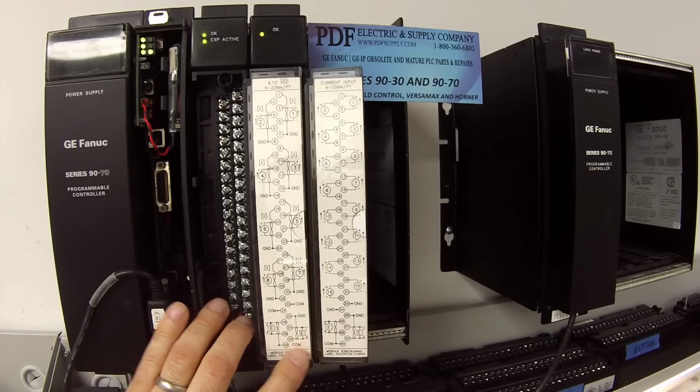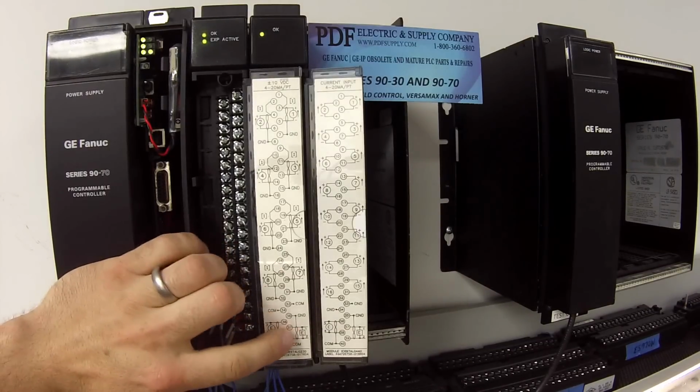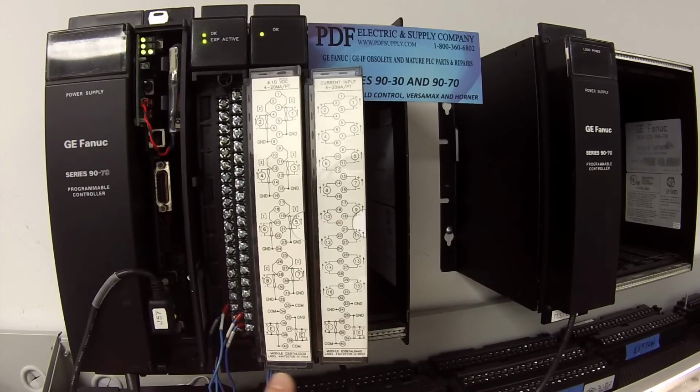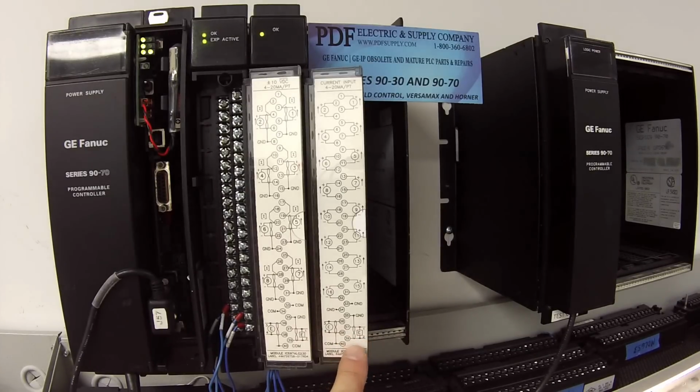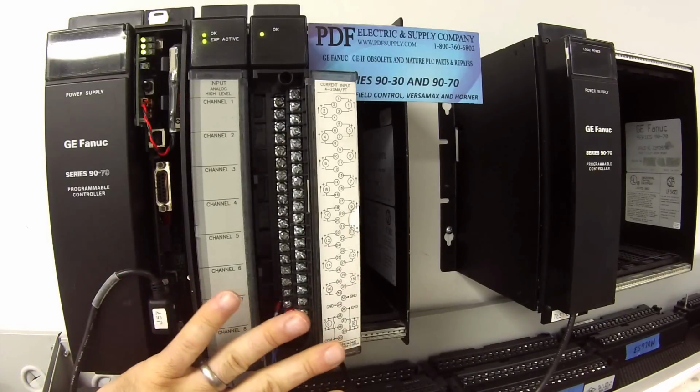You'll also notice these digits. Next to the circular E is 3 and 4, next to the square E is 1 and 2. What that's telling you is that you simply wire parallel from one module to the next in order to get this expansion capability. So I have my circular E3 going to my circular E3, which are both terminals 36. Circular E4 to 38 and 38 on the module next to it, and so on. E1 to 37 and E2 to 39. Okay? So this is a very, very simple parallel wiring in between the two modules. That's my physical configuration.